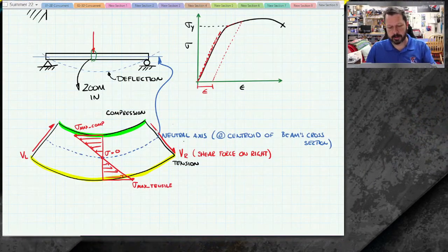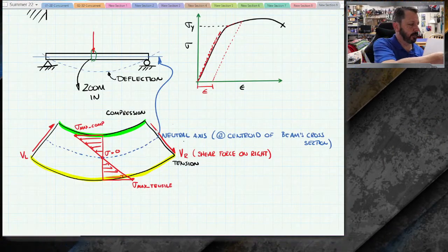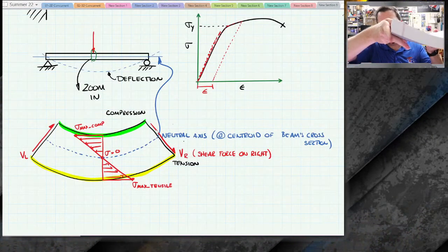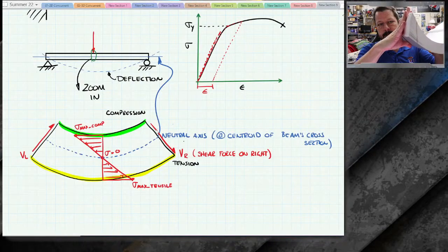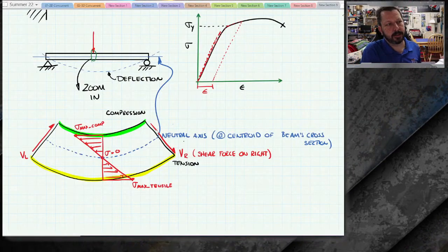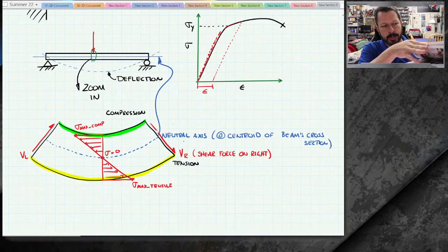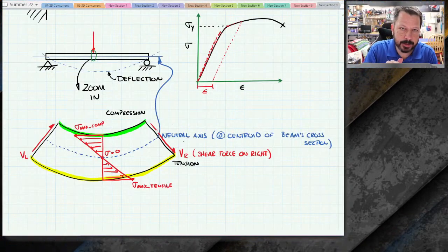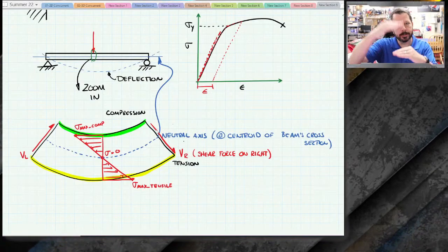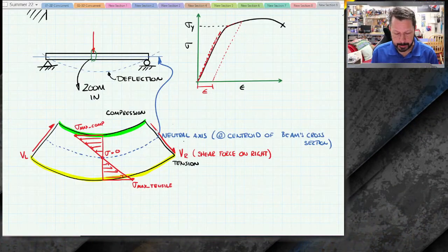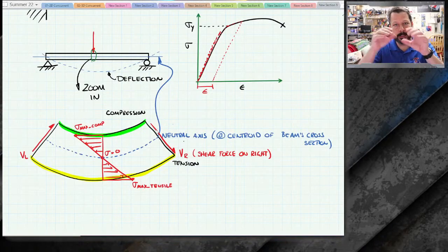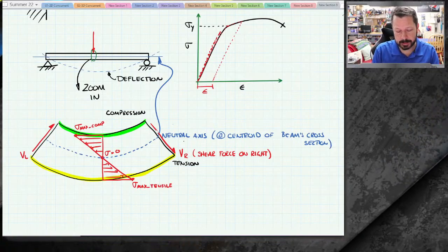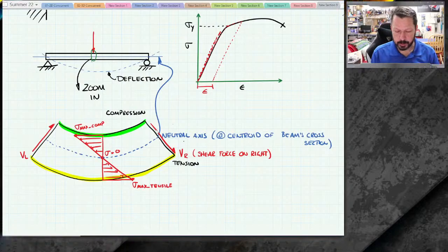So this is a book. Let's get the cover off of it because that's not going to do what we want. A book with a whole bunch of sheets of paper in it, if I bend those papers, you can see how they're not lined up anymore. So there is a shear force between every sheet of paper. Every sheet of paper in there has a shear force between those layers. Same thing would happen. I mean, beams don't necessarily have layers in them. They sort of have layers of atoms in their crystalline structure. And those want to slide past one another whenever you bend it, just like the pages in a book would. So that's also a shear stress that is in these beams that are bending. We're not going to worry too much with that one.